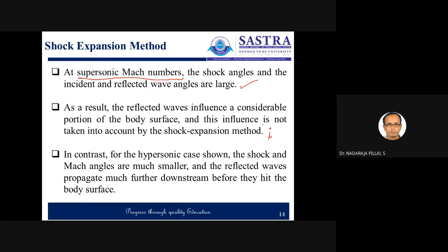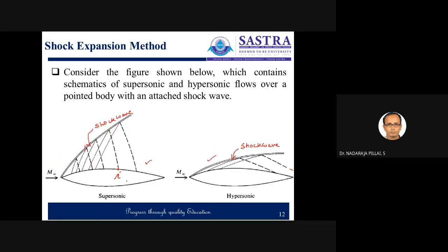But in the hypersonic case, the shock and the Mach angles are much smaller, and the reflected waves propagate much further downstream, right? Most of the time it does not hit the body surface. And if you measure the pressure at a point I, it will not have the influence of the reflected wave.